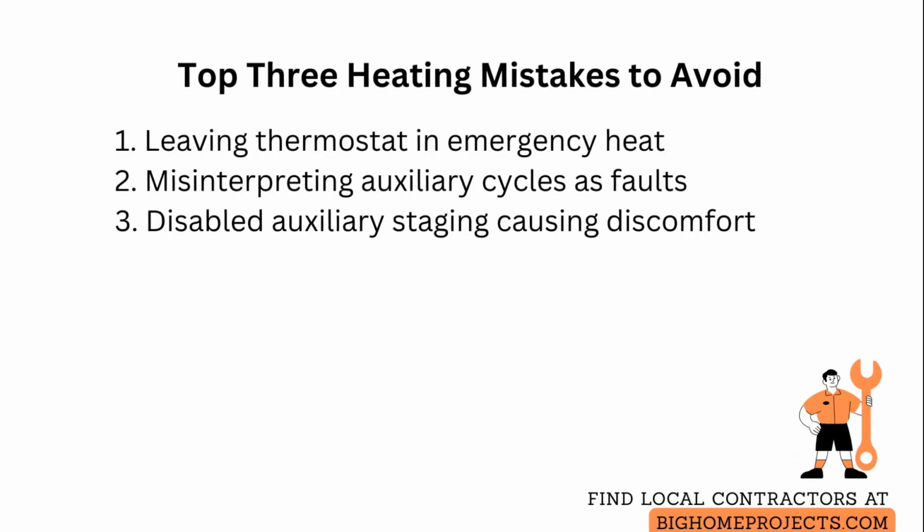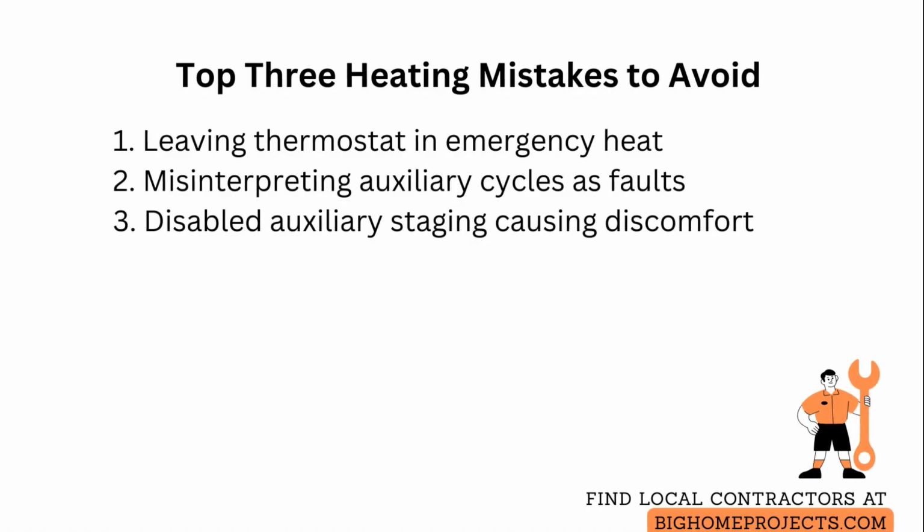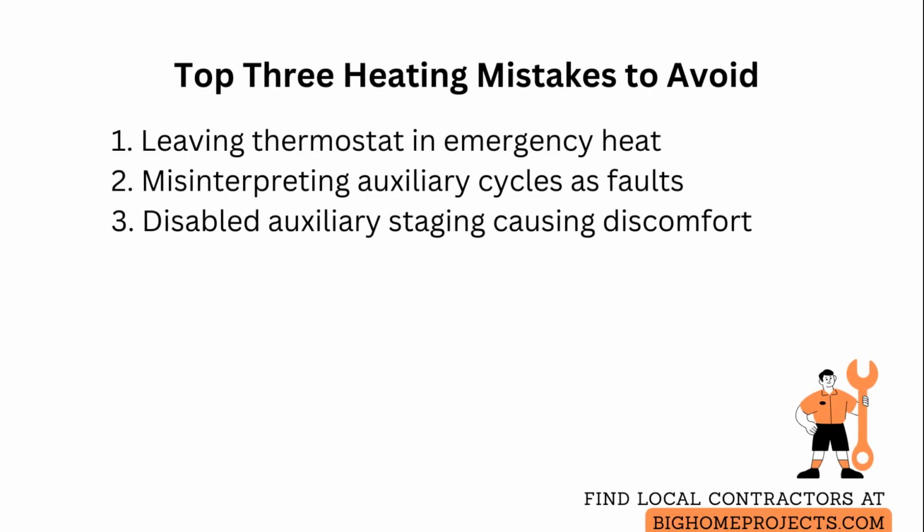People often leave the thermostat in emergency heat after a service call and then pay much higher energy bills, so always switch back to heat pump mode once the outdoor unit is repaired.